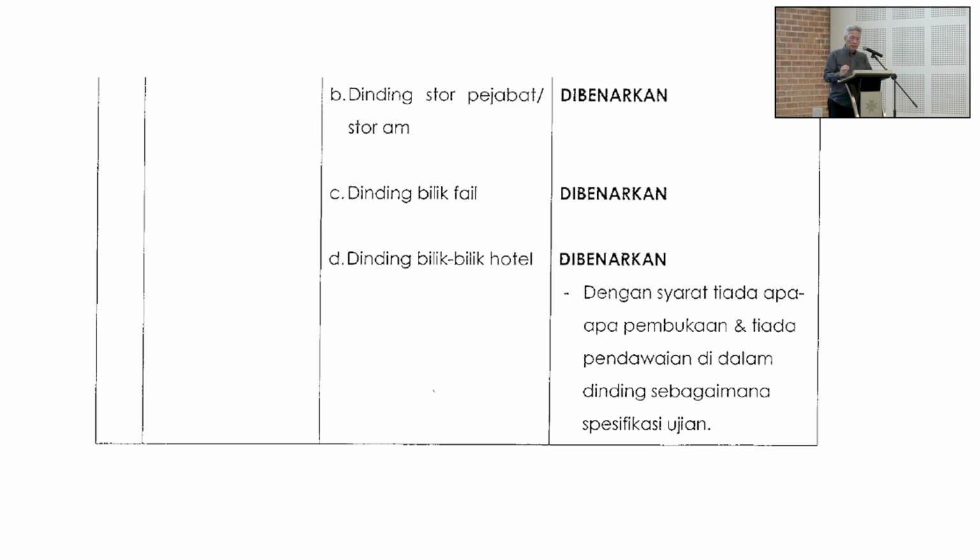And for hotel rooms, it's required. Hotel rooms fall halfway between individual maisonettes in the building and the overall compartment volume of a commercial building. Under purpose group 3, sorry, not commercial, it's other residential. So your hotel rooms are not necessarily going to reach anywhere near the limit of compartment. But likewise, you do have to have some privacy between the hotel rooms.